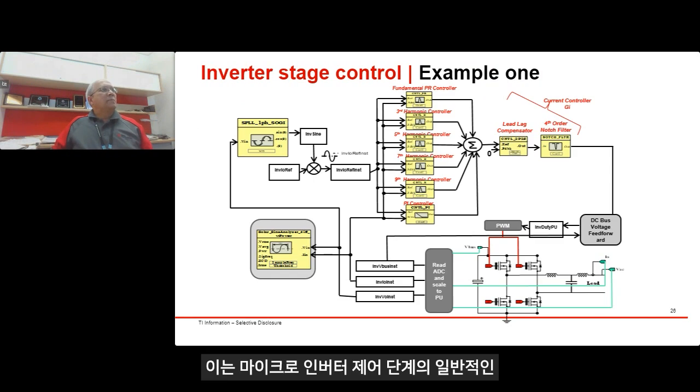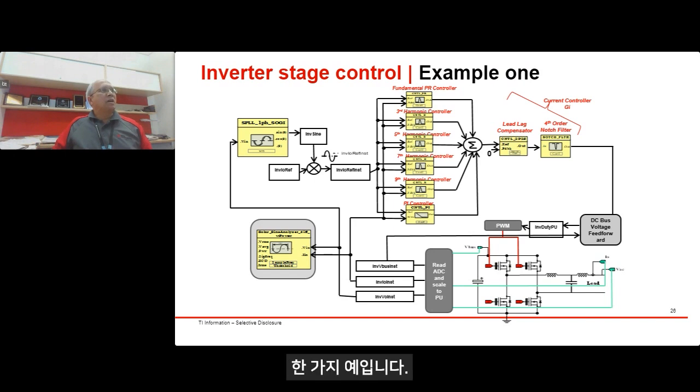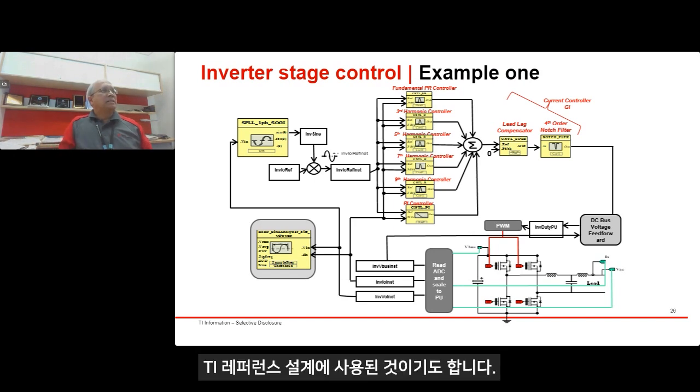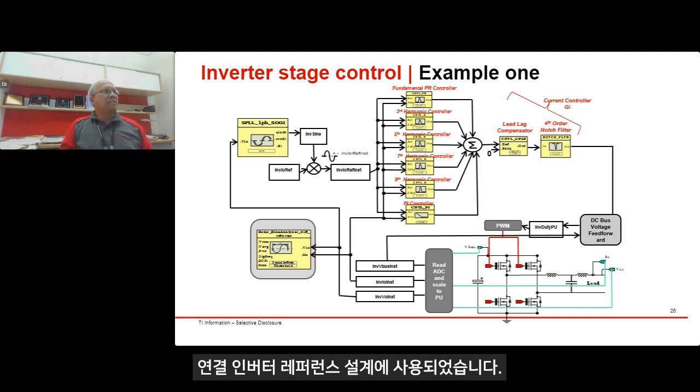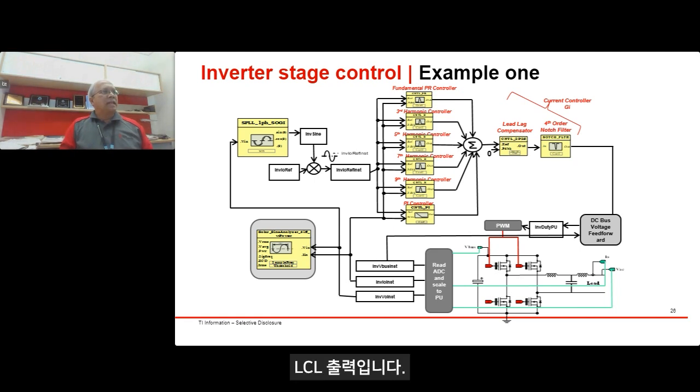This is a typical implementation of a microinverter control stage only. It shows one example, and this is what has been used in the TI grid connected inverter reference design. If you look at it, it's a full bridge inverter with the LCL output.